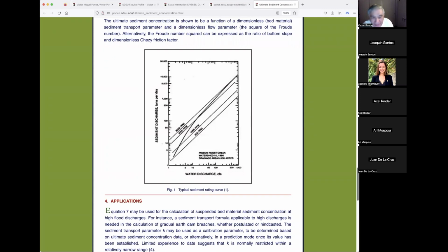Okay, so this is a sediment rating. What they said in there was that the sediment rating is going to have a tendency to achieve a constant concentration. Can you see that? Those lines at 45-degree angle are constant concentration. There's 500, 1,000, 2,000, 5,000 ppm of concentration of sediment. That's very thick chocolate, because when the water has 300, it's kind of clear, a little bit brown, but not so much. But by the time it gets to 1,000, 1,500, certainly 5,000, it looks like chocolate.